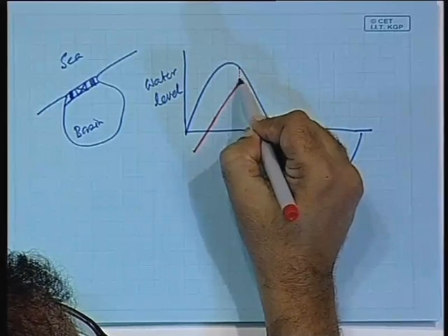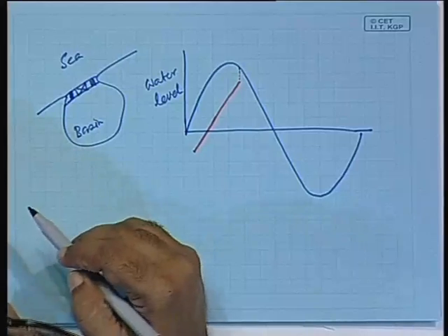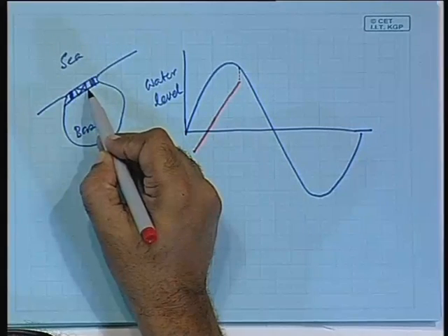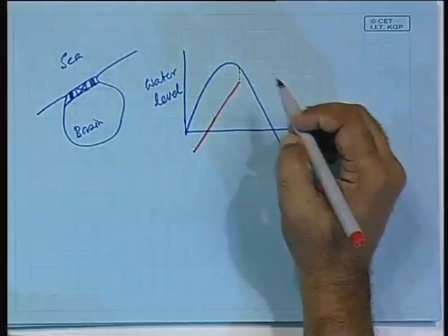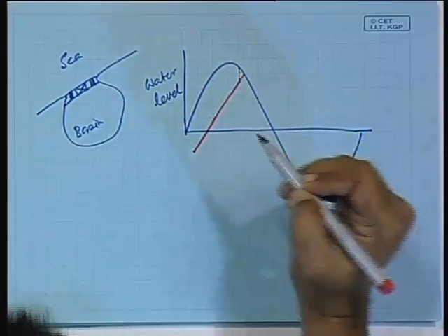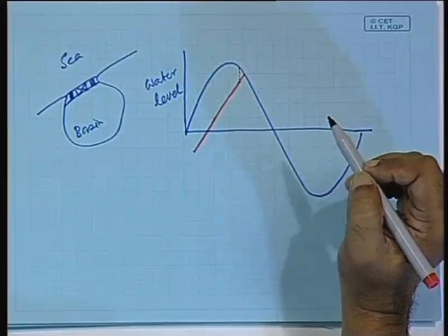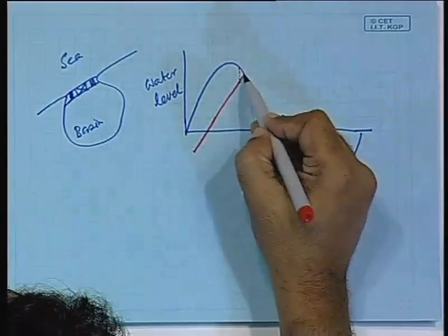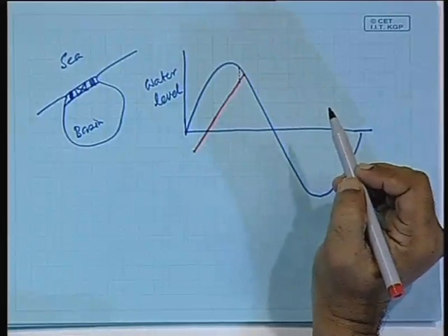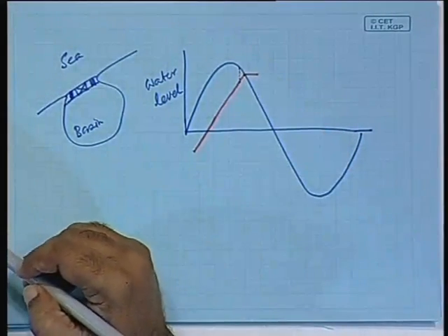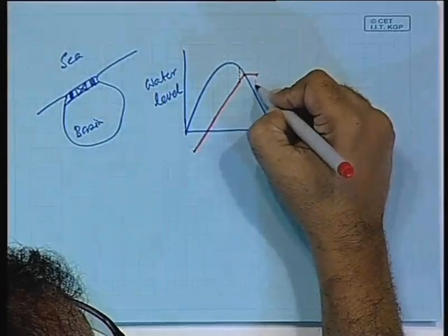When the head has become too low, you stop the turbine and keep both the turbines and the sluice gates closed, or you might open the sluice gates till it goes to this point. The turbine cannot function, but you can still open the sluice gates till the water levels become equal, and then both are closed till some time when again the head builds up.